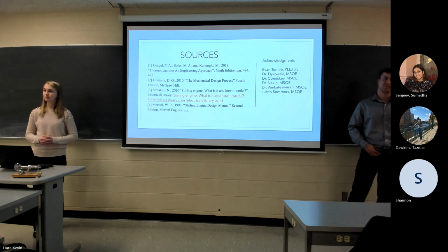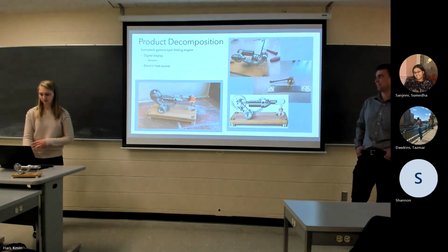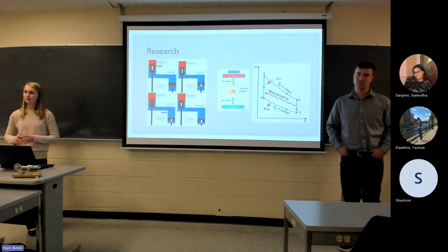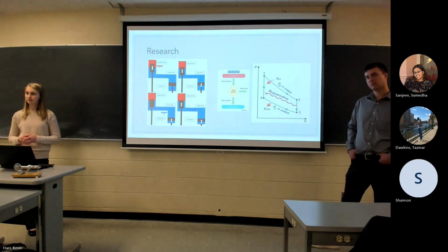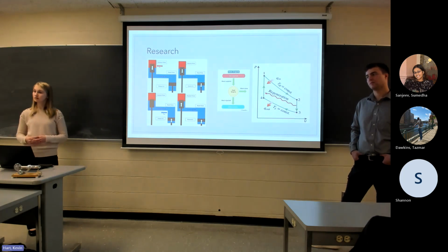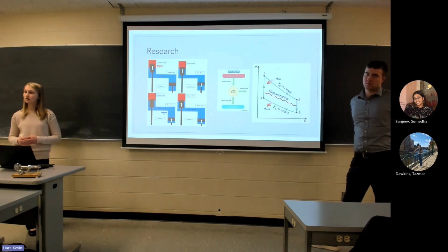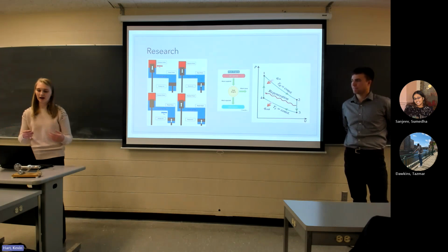Could you go back to the schematic of the Gamma Stirling engine? Sure. So there are two phases where the power piston is moving, but the displacer piston is not moving, right? And then the other two phases where they're both moving in concert to keep it as an isochoric process, right? So is that something that you talked about? How do you engage them and then disengage them? Does that make sense? Because you said that they were going to be connected through a flywheel so that they're moving in concert, but they're obviously not going to be moving in concert during the isothermal processes, right? Yes, so part of that has to do with the phase angle that they are operating at.